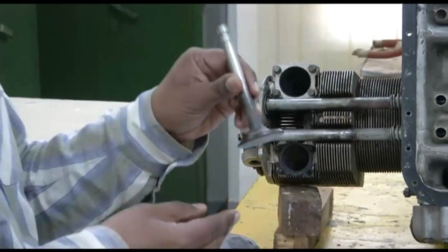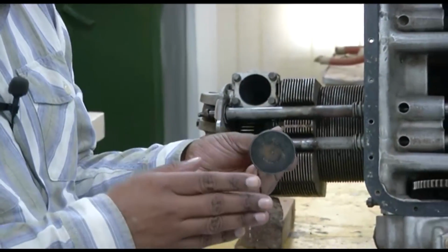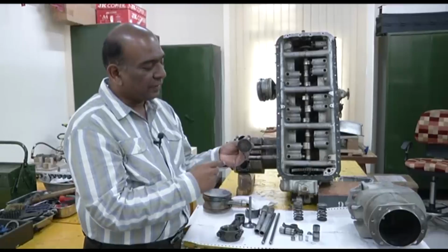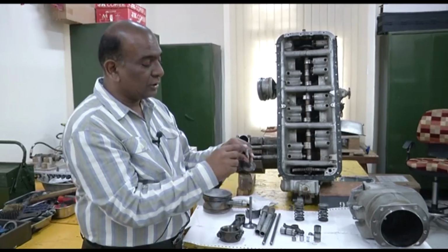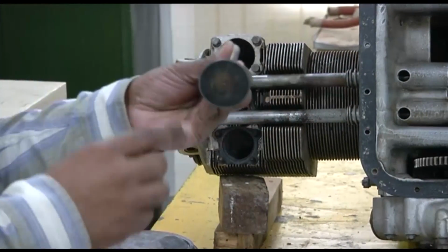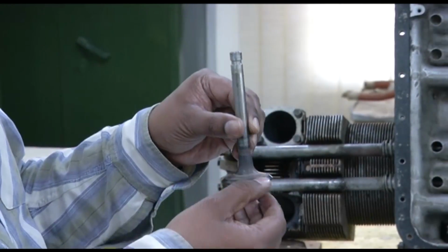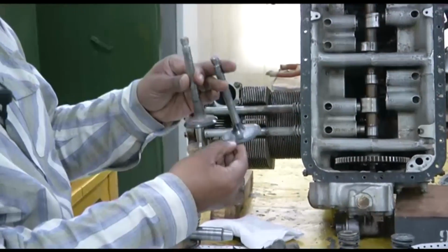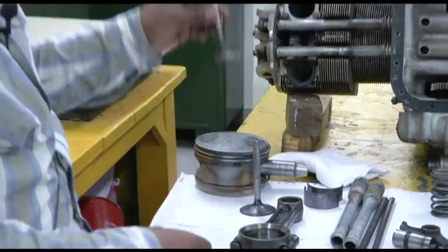We have seen that the exhaust valve, since it is exposed to very high temperatures and a corrosive environment, has its face coated with a hardened material called stellite. Also on the tip, because on the tip you have the continuous hammering of the rocker arm. At the same time the valve is ground to a certain angle. You can see the two valves, the exhaust valve and the intake valve, are ground to a certain angle, as we have seen in the class. So these are the valves.